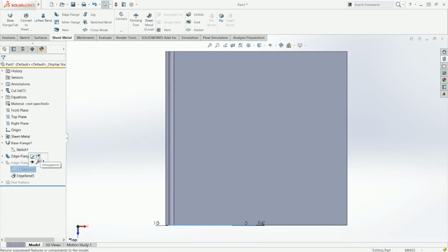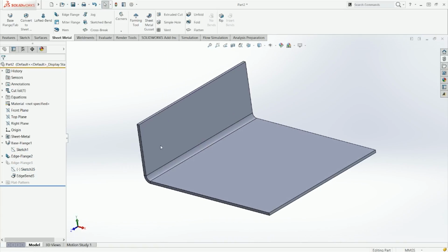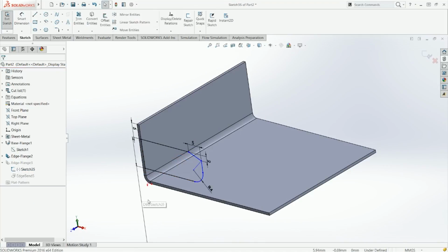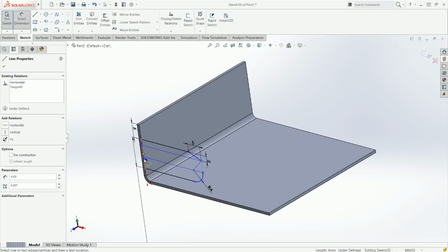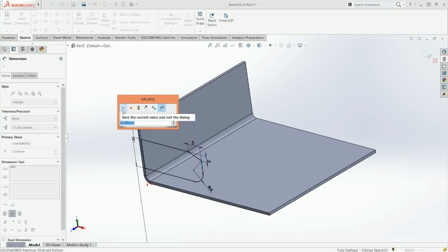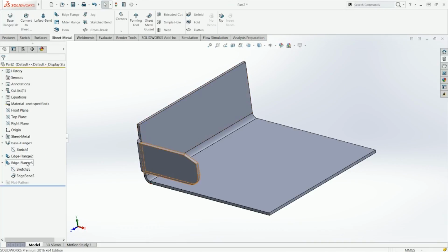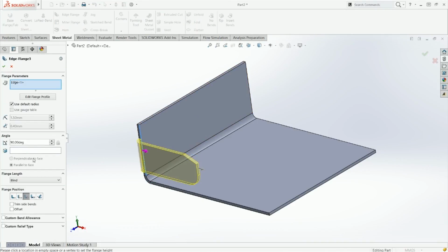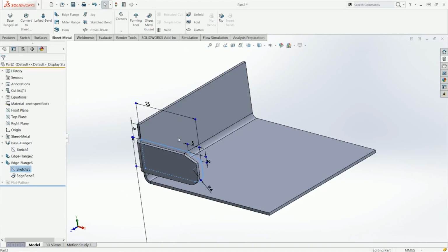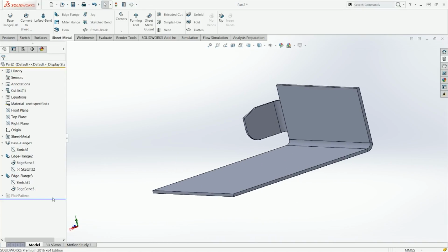SolidWorks recognizes that you want to edit the flange, and it tells you, okay, I'm not gonna mess around with what you try to do. So it lets you define it completely, so you don't have any issues. Now you can see that. And if you have the blind, you see you cannot define it anymore because you've actually broken that link. But no worries, because your sketch has the information there, so you can only change that now. So that's one way of defining a flange.